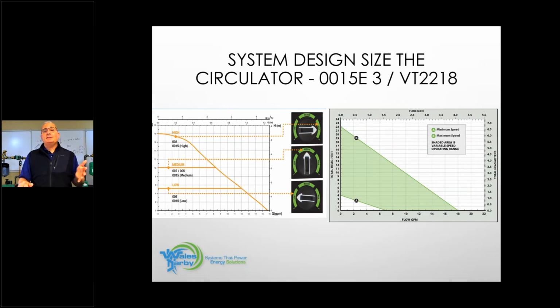And as the boiler changes its output, my T circulator doesn't care, because all it's going to do is maintain whatever temperature differential we put in there. So if my boiler is going to change its output based on the weather conditions changing all the time, and if my circulator also did the same thing, I should have level comfort through my home at all times. Mr. and Mrs. Smith would never know things are changing.